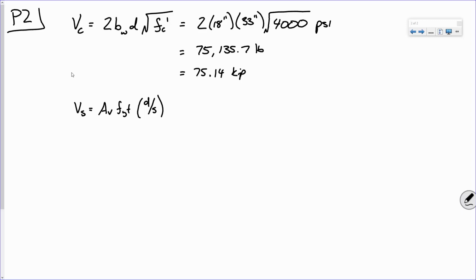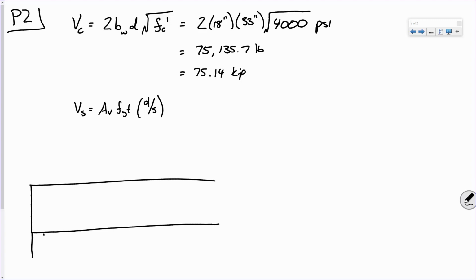It's twice that, remember? Because, remember, here's your beam, right? Let me go down here. So here's your beam. Here's the support it's sitting on. Here's the reinforcement steel. And here's all our stirrups, right? And remember, we assume that that beam cracks something about like that, right? Okay, so if I look, how many bars is that crack going to cut through?